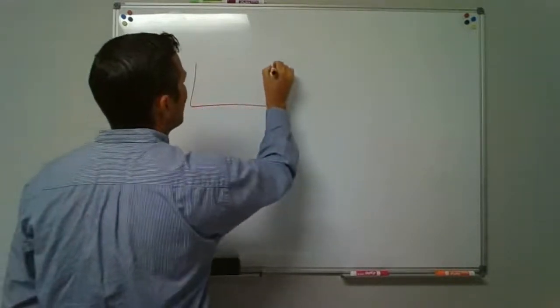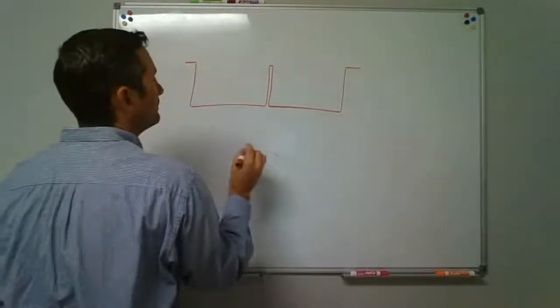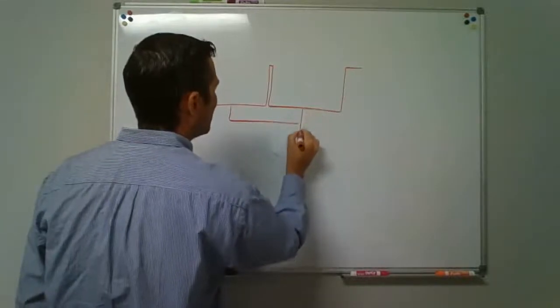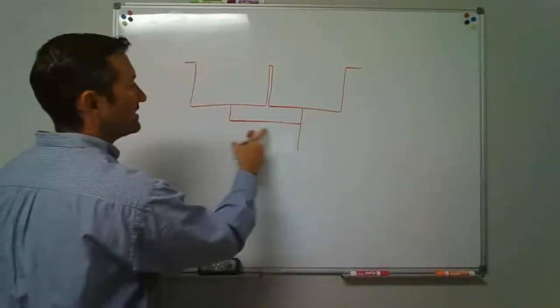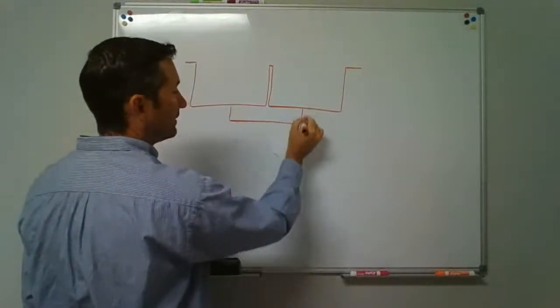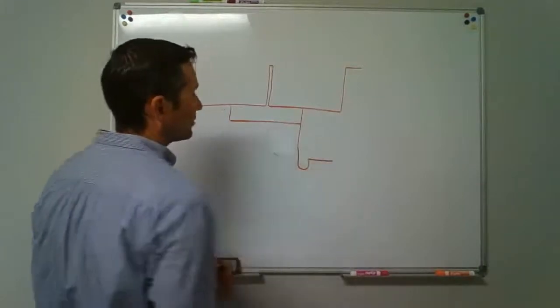underneath the kitchen sink. Let's just say you've got a 2-compartment kitchen sink here. Maybe you've got one that comes down and comes over and connects to this one. This is called a continuous waste end outlet. One is coming over out the end and connecting to the other one. And that will come down and have a trap on it and go back in the wall.